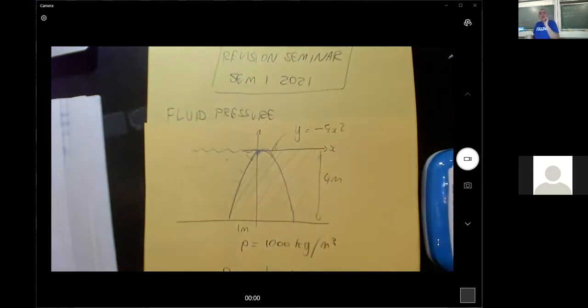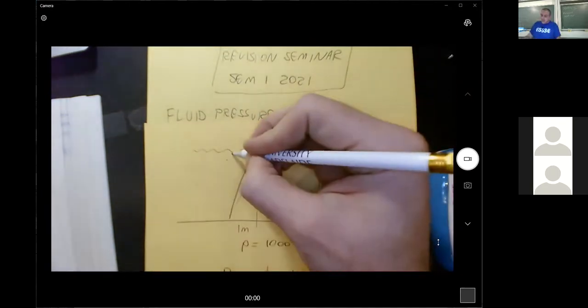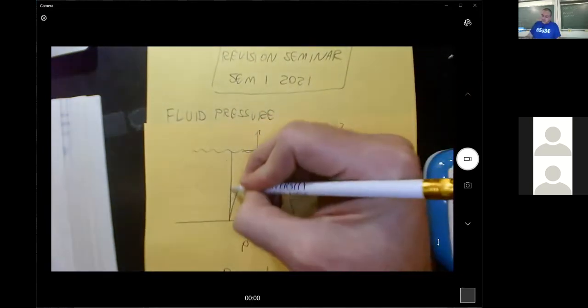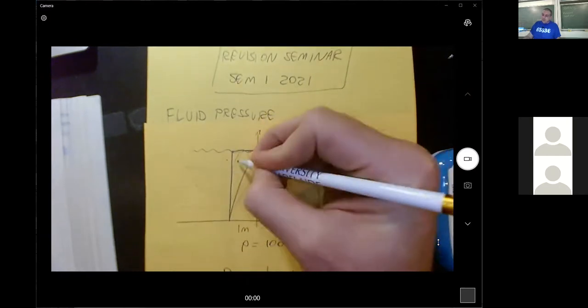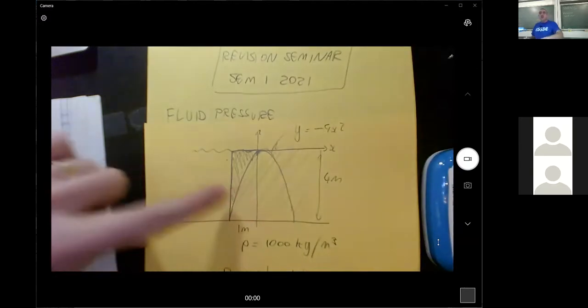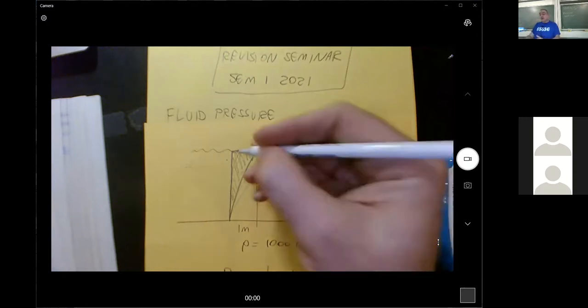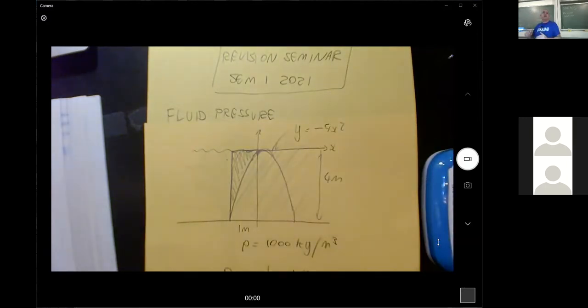But there's this really cool trick you can do where you can say, well, that's okay. The vertical piece will be caused by the weight of this water, and the horizontal piece will be caused by the pressure. That's the magic trick that we use, so we don't have to actually figure out pressures pointing in slanted directions.